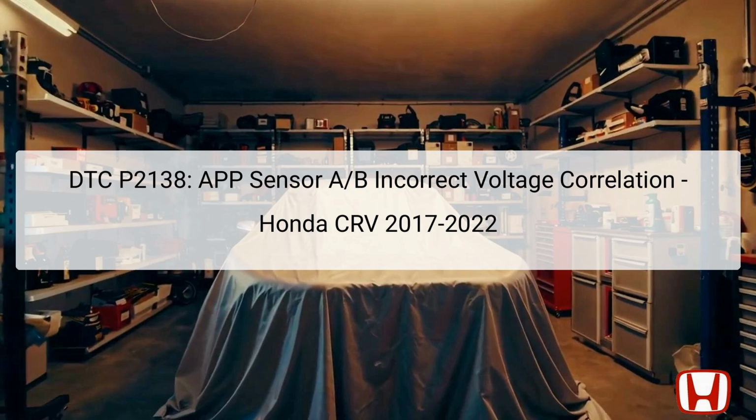The APP sensor plays a vital role in regulating engine throttle response, enabling smooth acceleration based on the driver's input via the accelerator pedal. Proper functioning of these sensors is crucial for vehicle performance and safety. Failures or discrepancies between these sensors can lead to erratic throttle response, possible loss of power, and in some cases, trigger engine limp mode due to safety features programmed within the vehicle's PCM. Therefore, it's essential to address P2138 proactively to ensure optimal engine management and vehicle drivability.